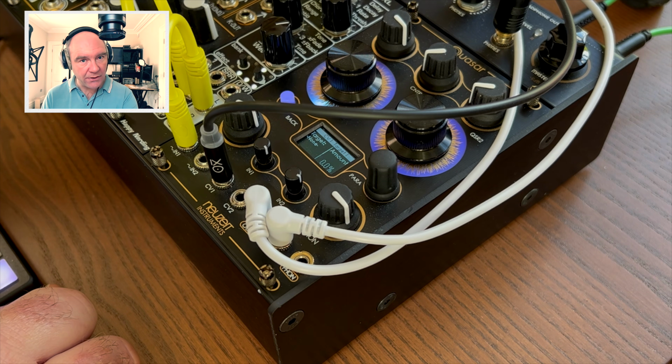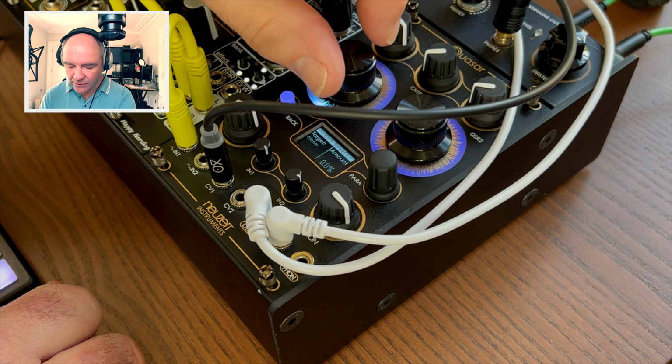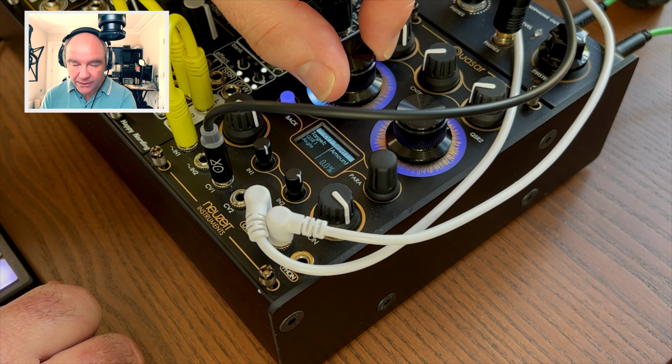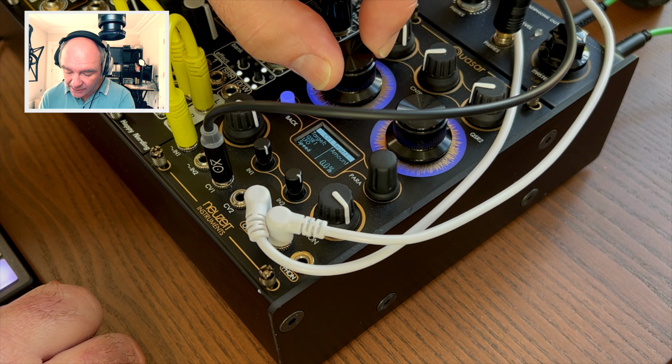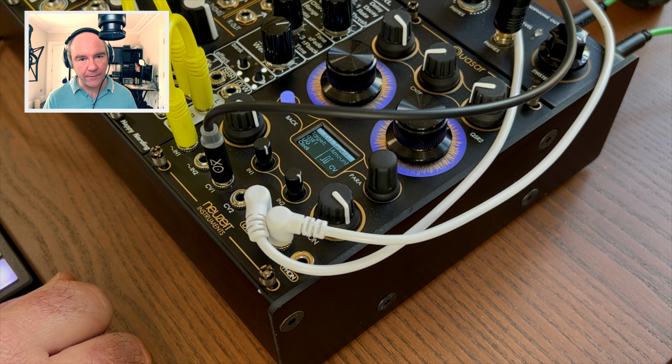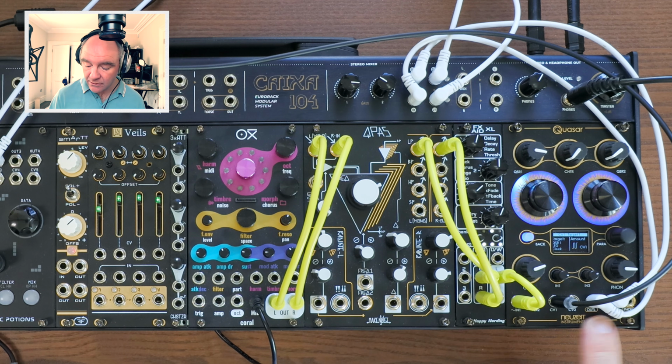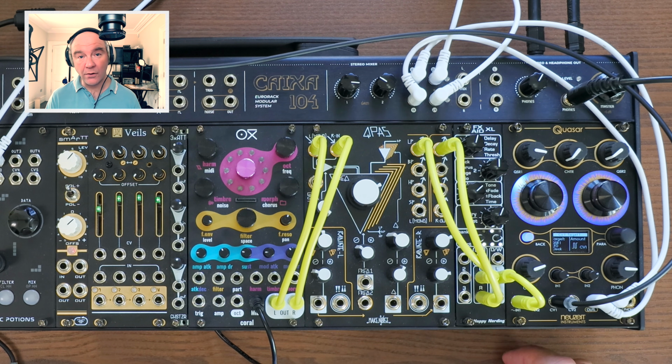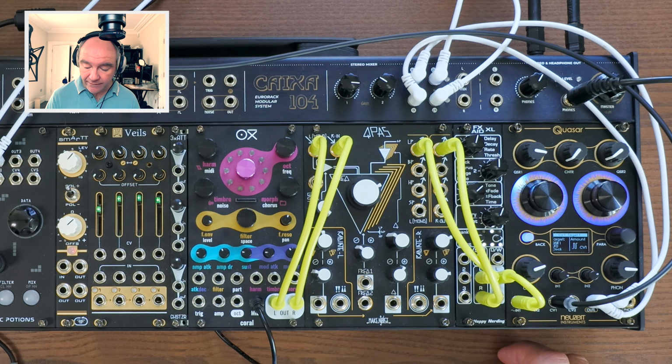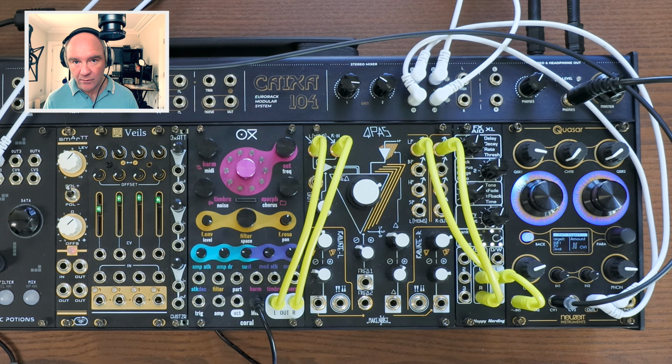Now if you wanted to just modulate the actual value directly, you could set the target to whatever you wanted to, height or angle. But we want to clock it, so we're going to rotate this knob here till we get to LFO clock. Each CV value, each control voltage value, can have up to 4 targets. So you could also clock the LFO, say, for Quasar 2 off CV1, or you could map it somewhere else. So if you had a value coming in here, you could map it to multiple parameters in the Quasar at the same time, which is actually quite nice because it saves you having to have multiple patch cables flowing around.